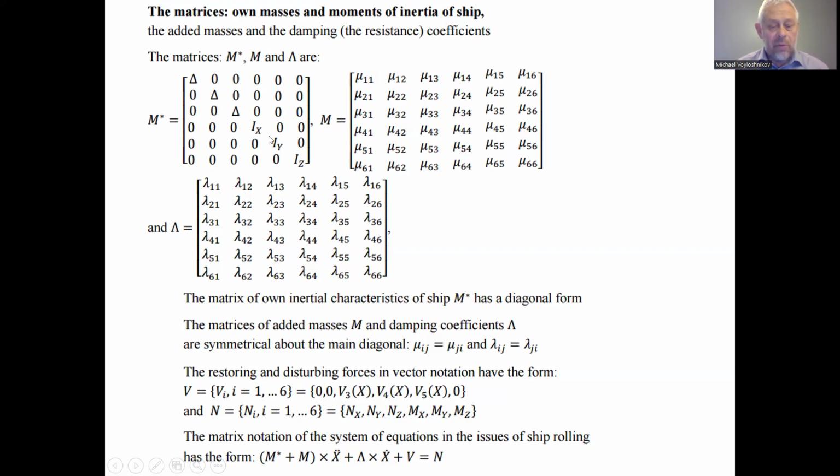and the moments of inertia are characteristics of the ship inertia in rotational motion. The first index indicates in what direction we consider the impact of the inertia of the ship on behalf of water. And the second index means in what direction the ship moves with acceleration caused by the force arising in the forced acceleration. This is how the ship's transverse direction motion impacts its inertia in the force direction.